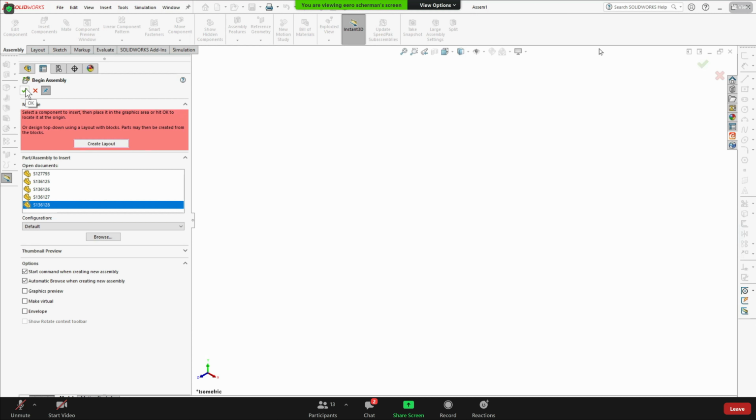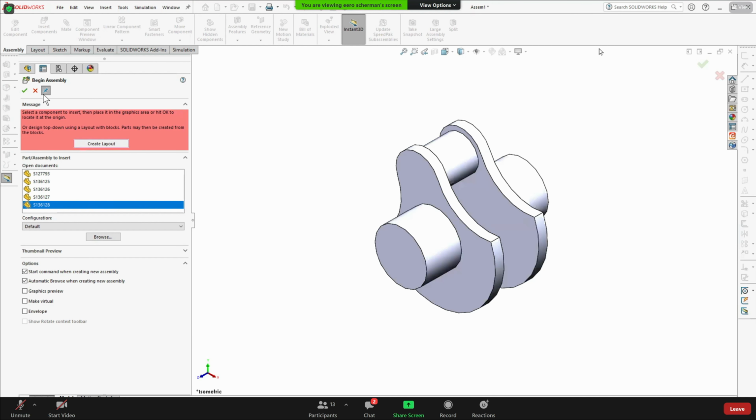Oh, yeah, Sima told us about this, I guess. The part will appear on its basic position, like relative to the original drawing. And I think what you're leading to is that if we click all the parts and then press OK, they will automatically arrange in assembly because they are derived from one sketch. Am I correct? Correct.